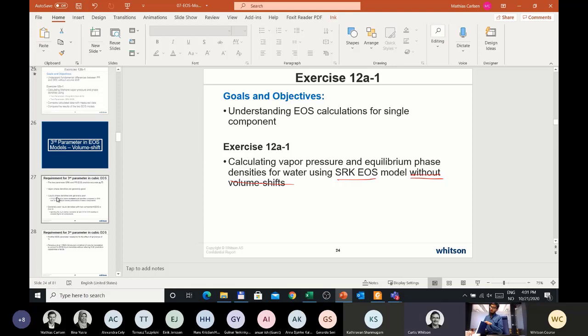So what you have to do is artificially change the water and/or rock compressibility to give the correct total compressibility, so that you get out the right amount of fluid as you deplete the pressure. That's been done in a number of cases in HTHP reservoirs. Again, it's a manual exercise to get those water and/or rock compressibilities to change as a function of pressure such that the total system compressibility is changing correctly. Those are your three options.